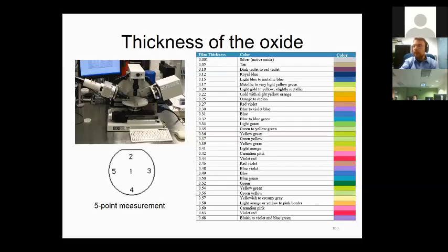But the formal way, as we will cover in the afternoon, is using an ellipsometer. This is our ellipsometer from our tool. I will talk more about it, but there is a laser source here on this end, and there's going to be a photodetector. That's like the generic type ellipsometers. And based on the reflection phenomena here from the laser to the photodetector, we try to understand reflection from the wafer here, the wafer that's sitting in the center.